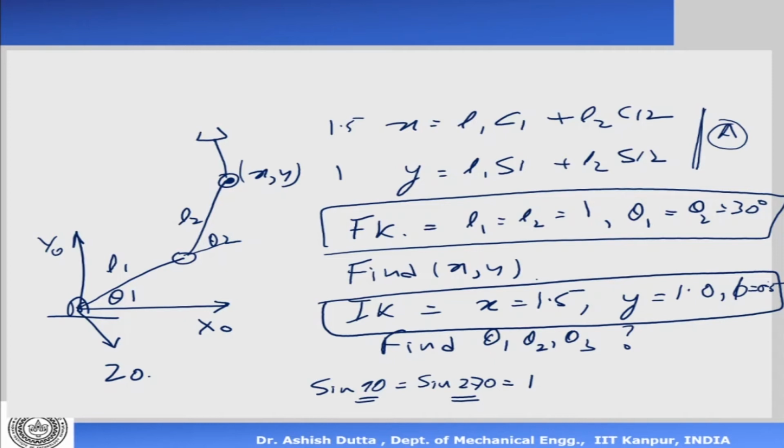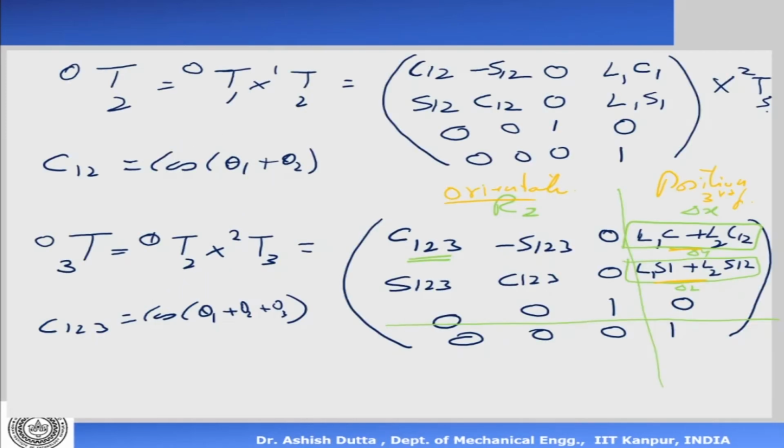Okay, here let us proceed and just find out the relation. So this is basically forward kinematics and inverse kinematics. Now let us see how we do the inverse kinematics of this two-link manipulator system which is required for us. Very simple example again. Let us look at this two-link. I'll further simplify this. So this is my two-link manipulator system. This is my theta 1, theta 2, theta 3. And my final matrix has come in the form, you remember what the final matrix was. In the final matrix what we got was x is equal to that and y is equal to that. So I can solve theta 1 and theta 2 from here and then theta 3 from here. So what I do is I first write down x and y and try and solve for theta 1 and theta 2.